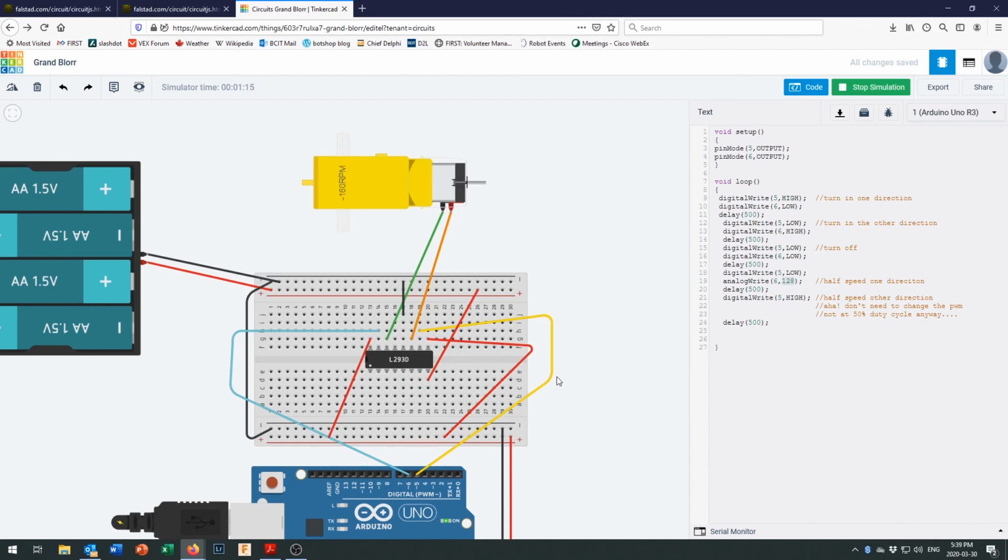So that's a pretty cool feature about the TinkerCAD simulator. So those are 2 examples of DC brushed motors, and you've certainly got the opportunity to build another brushed motor in right here and control that brushed motor maybe by using an ultrasonic rangefinder to have the motors spin forwards until you come to a stop. Have them spin forward until your range becomes too short and then have the motors turn off, or have one motor keep going forward and the other motor start going backwards so that you turn until you've got some range and then your robot could go forward.